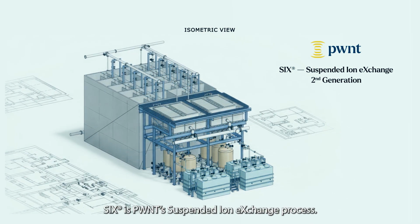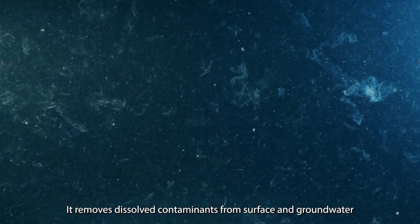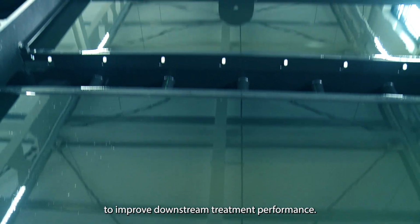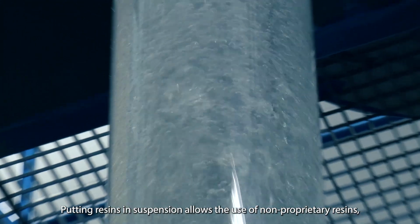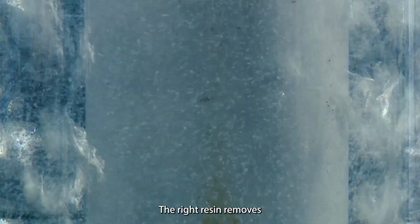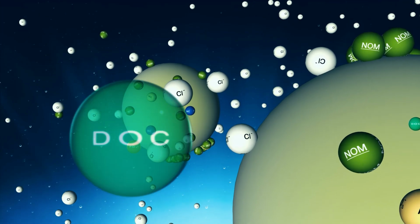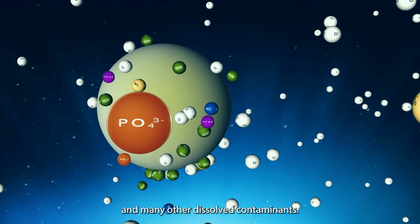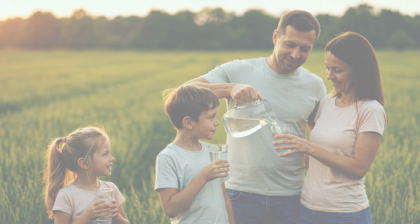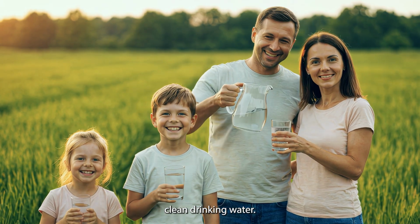6 is PWNT's suspended ion exchange process. It removes dissolved contaminants from surface and groundwater to improve downstream treatment performance. Putting resins in suspension allows the use of non-proprietary resins, each selected for a specific treatment objective. The right resin removes natural organic matter, dissolved organic carbon, PFAS, sulfates, nitrates, phosphates, and many other dissolved contaminants. The result is more reliable, more efficient production of safe, clean drinking water.